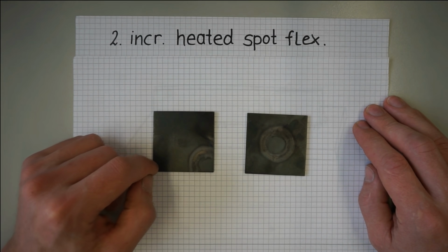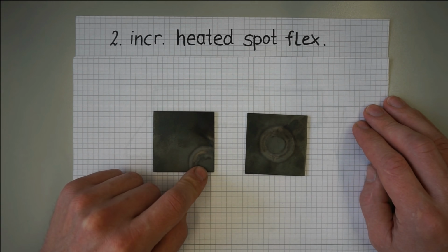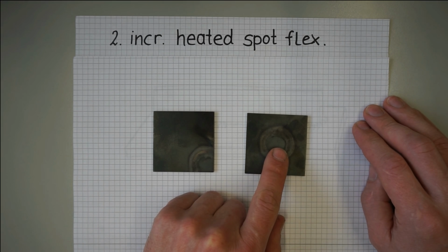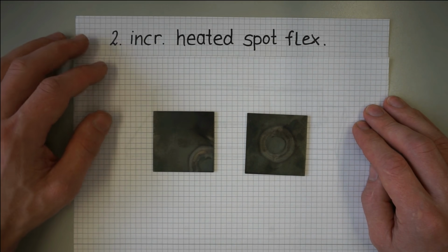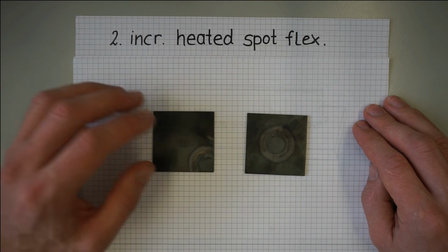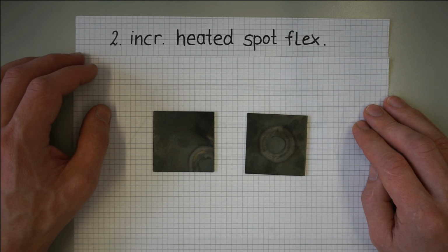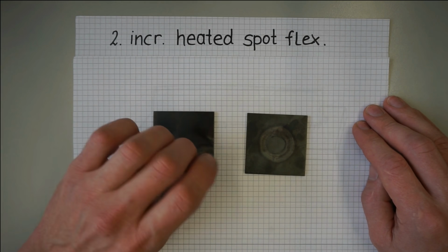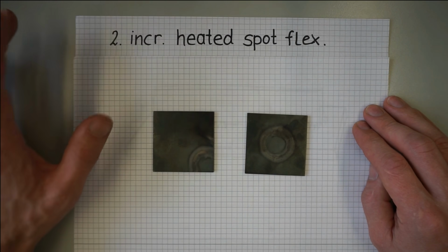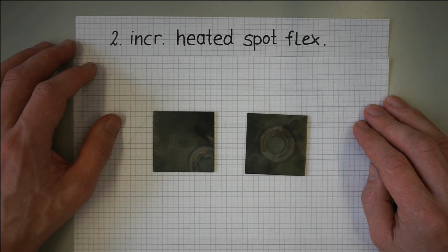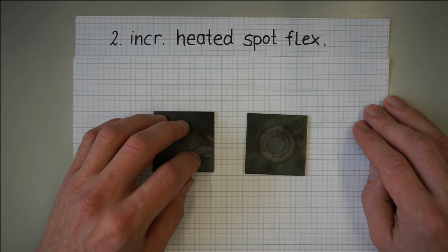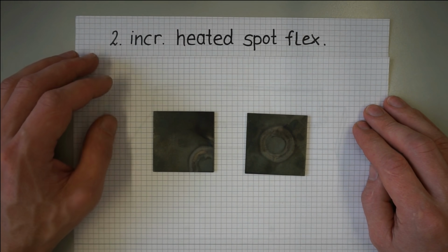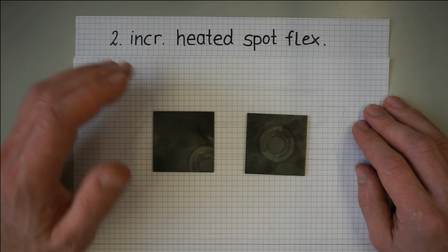We already know why this is. Here the heated spot's thermal expansion was much less constrained than here. The result was little stresses during heating and therefore little plastic strains. Allowing the heated spot to expand freely in ideally all directions is the essence of the strategy. We can basically implement this by having small welded joints and rather open designs, such as frames in comparison to hulls.